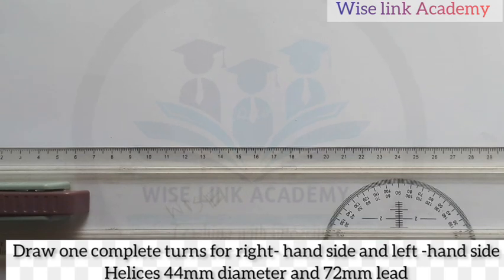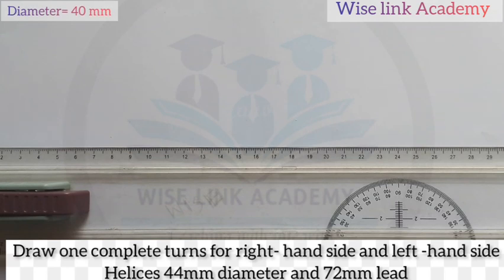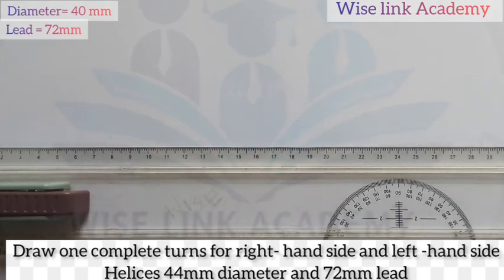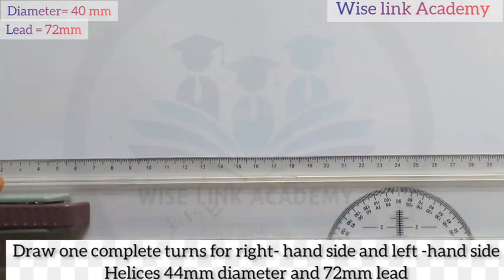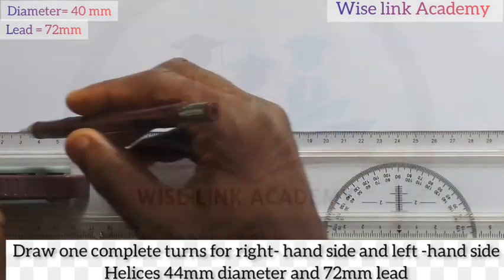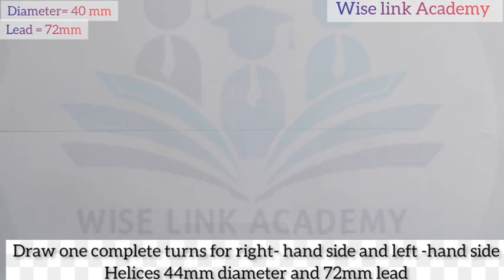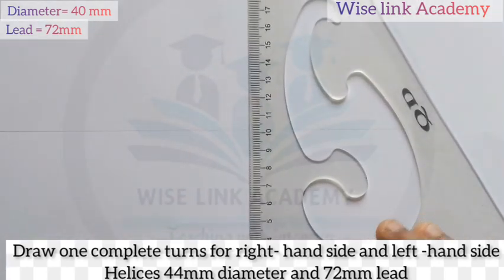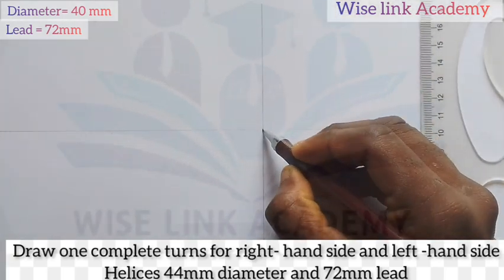So, from the question, I am given two parameters. The first one is diameter, which is 44 mm, and the other one is the lead, which is 72 mm. Now, my first task here is to draw a horizontal line and a vertical line. I take my T-square this way and draw a horizontal line, and also take my T-square to draw a vertical line downward this way. Where they meet is at this point.